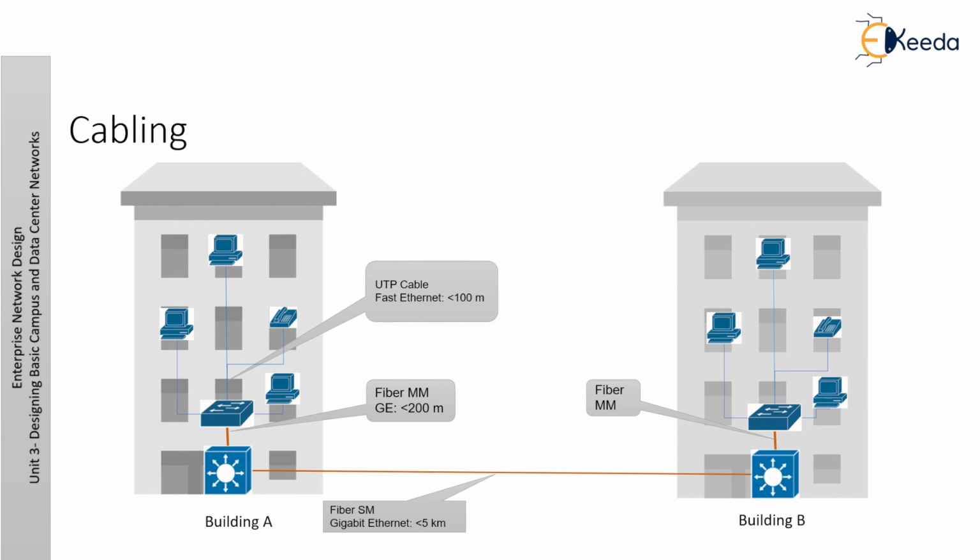Multimode optical cable is usually satisfactory inside the building. Depending on distance, organizations use multimode or single mode optical fiber for inter-building communication cable. If the distances are short, up to 500 meters, multimode fiber is a more reasonable solution for speeds up to 1 Gbps. However, an organization can install single mode fiber if its requirements are for longer distance or if there are plans for future high speed, for example, 10 Gbps.